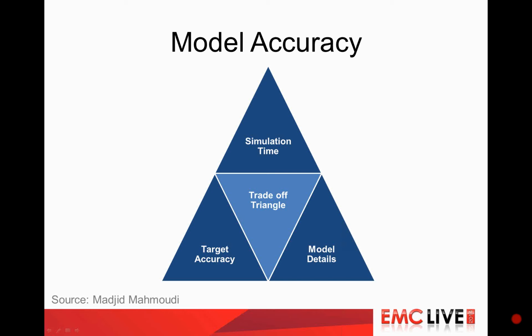And there is always one rule that I give to everybody who wants to start with simulation, and this rule is very simple: start simple. Start with a simple model, start with the easy model, and then increase the complexity of your model. Do not start with a model trying to put everything that is possible into it, because that's not efficient to do. Always start simple and increase the complexity.